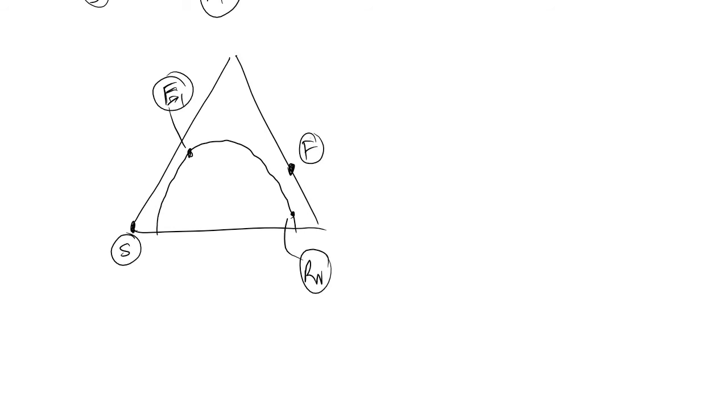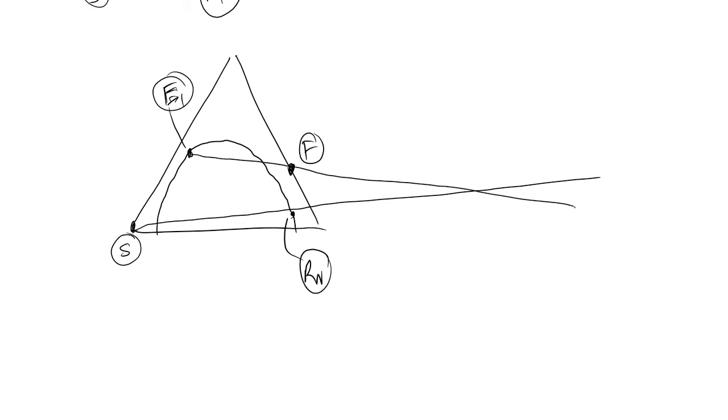I'm sorry, what I meant to say was we will actually connect S, R_n and the line E1, F to evaluate our pivot point P, like so. If we extend this line out, S R_n, and we extend the line E1 F, we'll find that they intersect at some point outside of our equilateral ternary diagram at point P. With this point P, we can now proceed to the next step of actually counting off the number of trays that will be needed in our system.